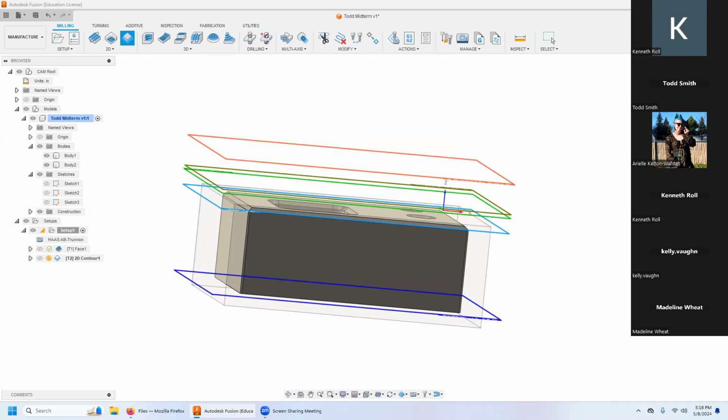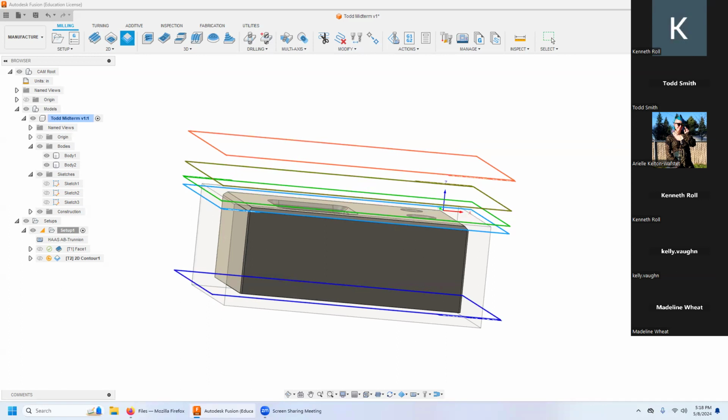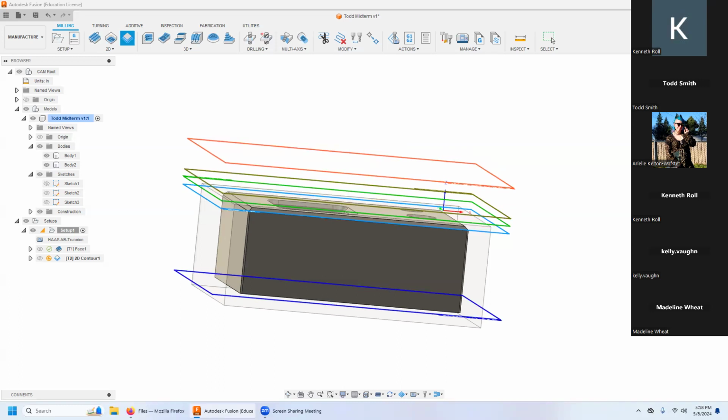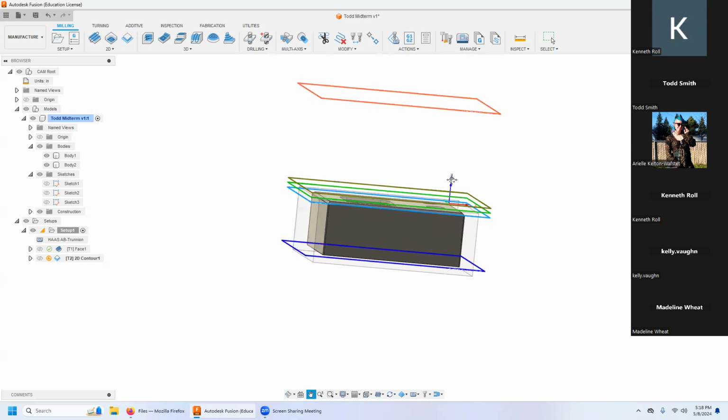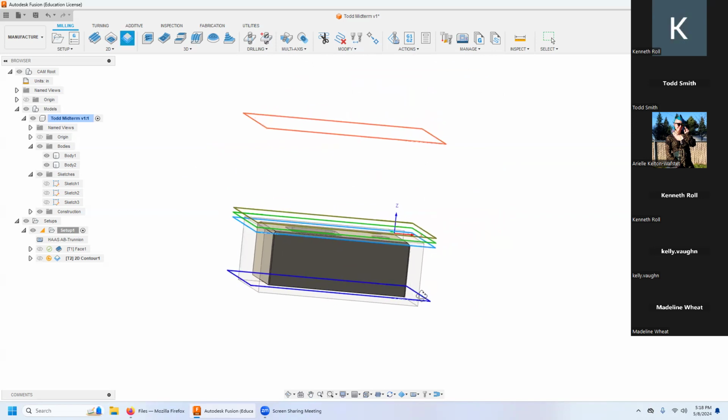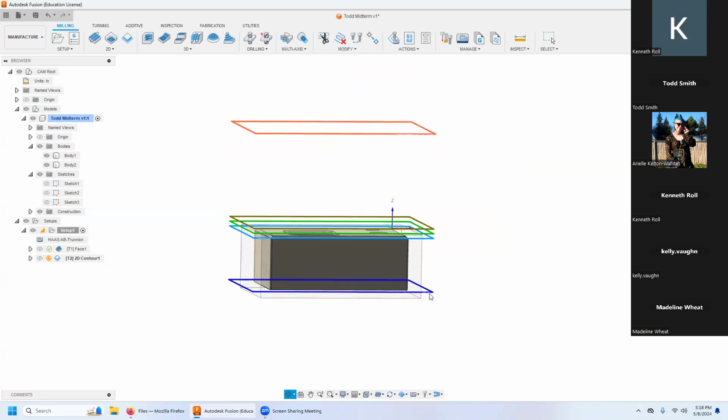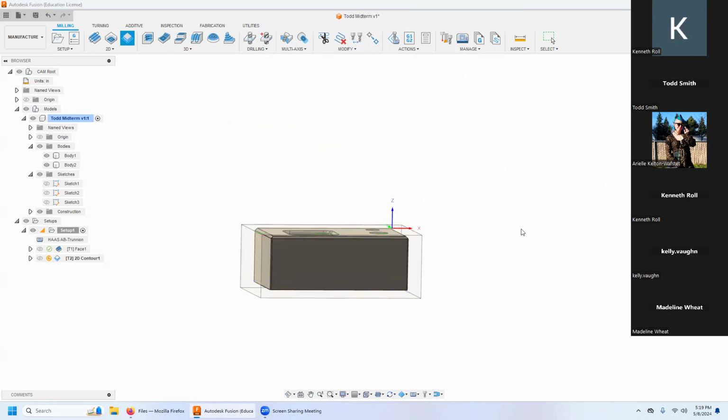And then feed height is going to be top height plus a 0.1. And retract is going to be feed height plus a 0.1. And my clearance is going to be my retract height plus 2 inches. Okay. So you guys should be pretty familiar with this at this point. I use pretty much the same values every time. You don't have to do the same thing. We're not going to do anything with machining type.